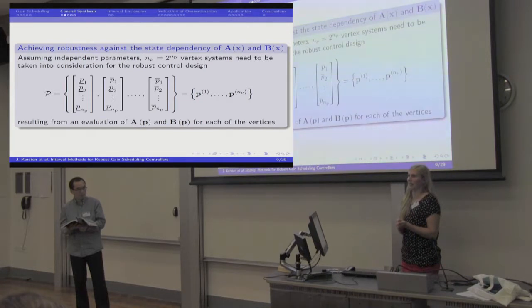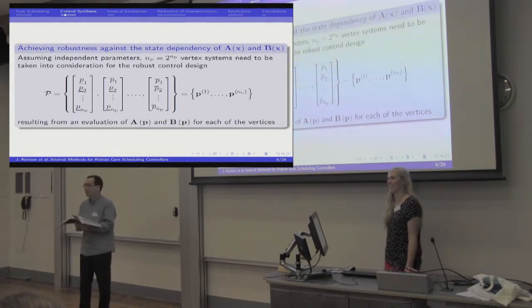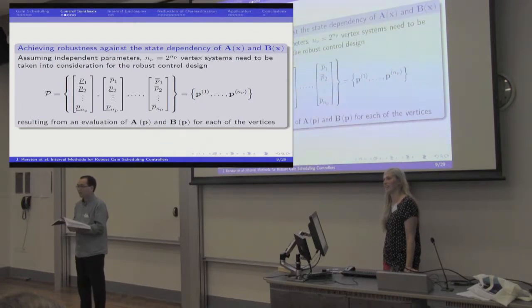May I give a short comment there? The very first stage is that you're calculating, regardless of the controller gain, a bounding box. This bounding box is being calculated with a Picard iteration, and you're then computing a controller gain that is stabilizing the system dynamics corresponding to this overestimated reachable set of states. If the computation of the controller gain fails at the beginning, then we have to stop. Therefore we know that there exists a Lyapunov function that is proving asymptotic stability, because otherwise the very first design stage would fail.